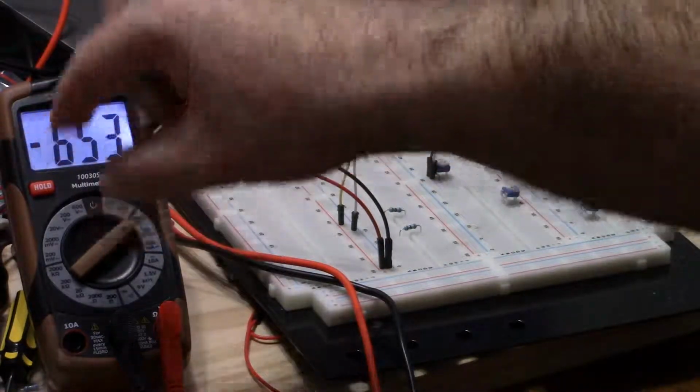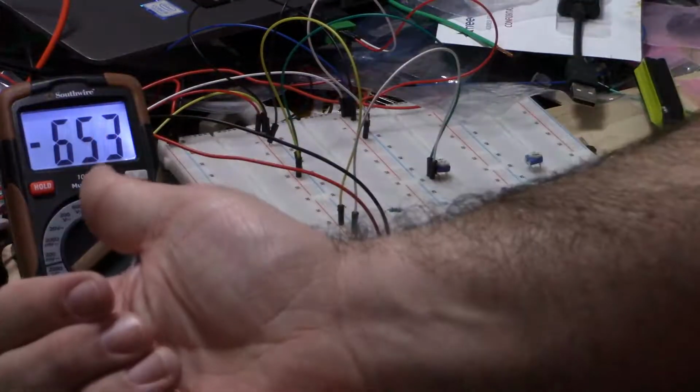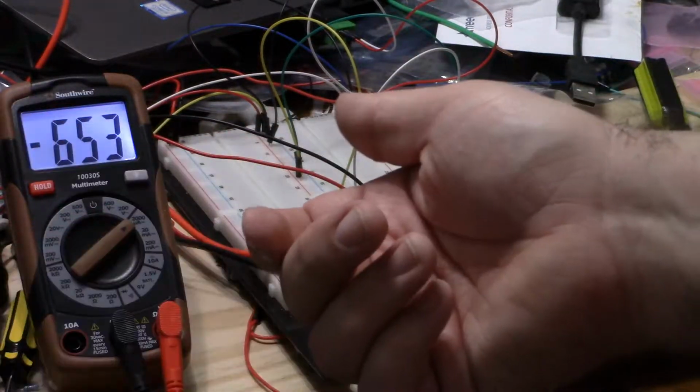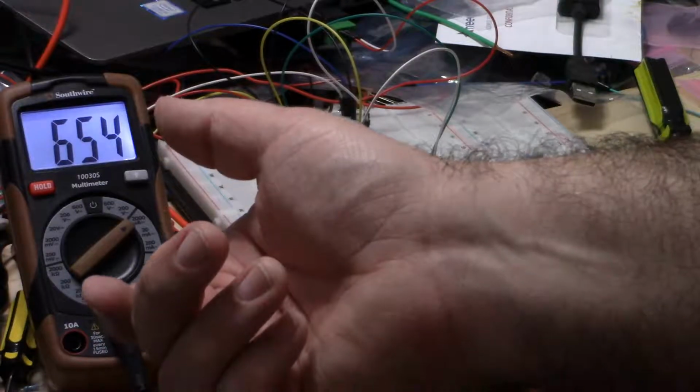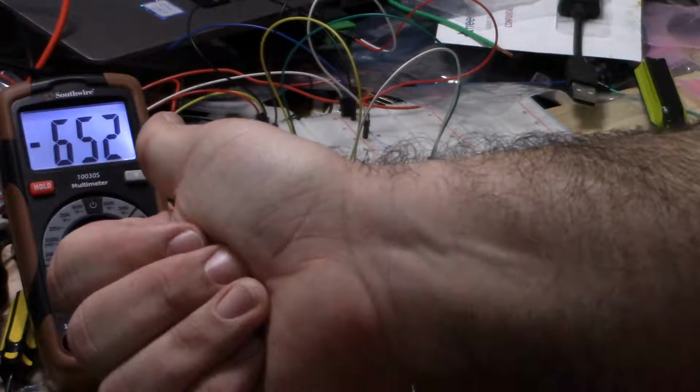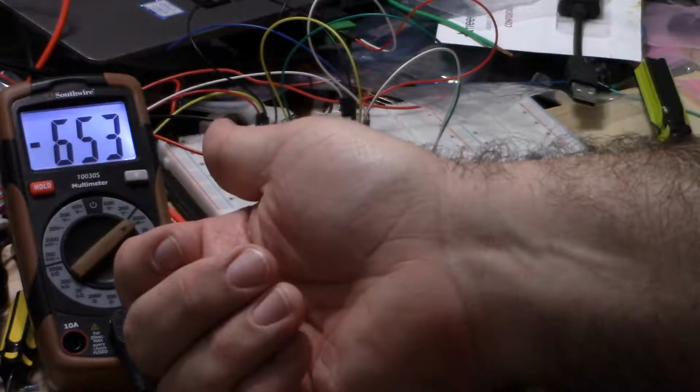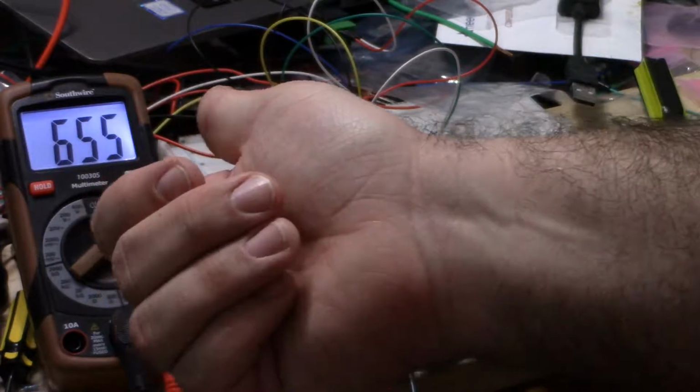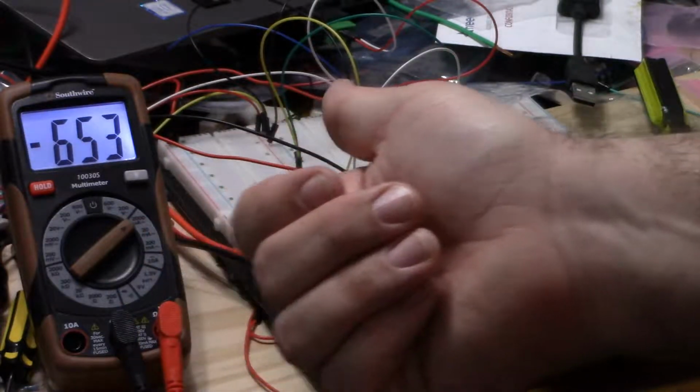The lower the resistance of the load plugged into the headphone jack, the lower the voltage drop, which is exactly as we would expect if you recall the series resistance formula. So there must be a resistor, naturally or artificially, probably naturally, in the output port, so that if you short across, it's not going to hurt anything.